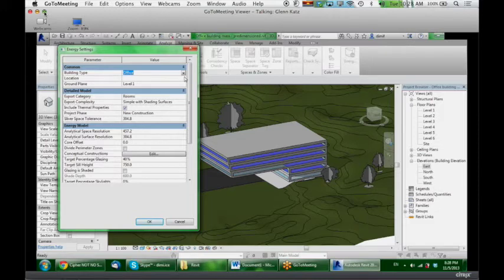So even as we're thinking about a building, we can subdivide it. A classroom is a lot more dense in terms of the number of us and how much energy we're generating than a typical office space, because we're pretty tightly packed in here. An auditorium is even worse because we're all packed in there. But then again, we're not all that active in the auditorium. So it's timing, it's density, it's the level of activity going on and how much energy that might be. It's all buried in this notion of building type. We can control it in more fine detail later, but at a high level, it's all tied up in that.